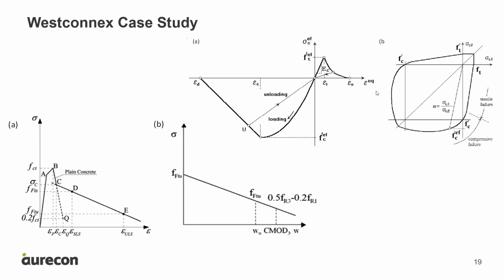For your constitutive relationship, you have a volume description because it's a relationship between strains and stresses. But when you have cracks, it's an area phenomenon, and that means that we get what's called size effects, and that also means that, for instance, the energy dissipation will be dependent on the size of the elements. So when we discretize, you have to be really careful if you change the sizes of these elements, because you'll get different results. If you make smaller elements, you'll get a larger load-bearing capacity. Yes, you're absolutely correct. These models are mesh dependent, so you have to do some calibration, and you have to be careful that when you calibrate, you are using the same mesh elements.